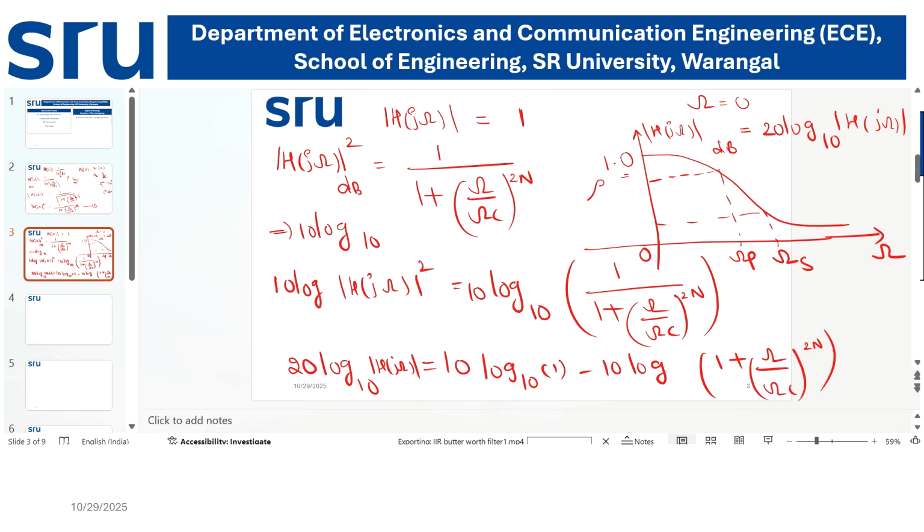At the passband edge we have the passband attenuation alpha p, and at the stop band edge frequency we have the stop band attenuation alpha s. Remember, the gain is 1 for omega equal to 0. When omega becomes omega p, we have the passband attenuation alpha p. At omega equal to omega s, we have the stop band attenuation of alpha s.